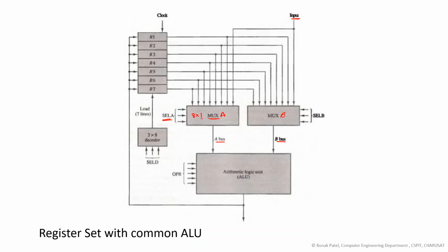Suppose you want to select this one input here. In that case, your selection must be 0, 0, 0. Now this is your S3, S2, S1, S0, and this is carry in. While you are performing an arithmetic operation, you require this carry in, but for a logical operation, there is no use of carry in.